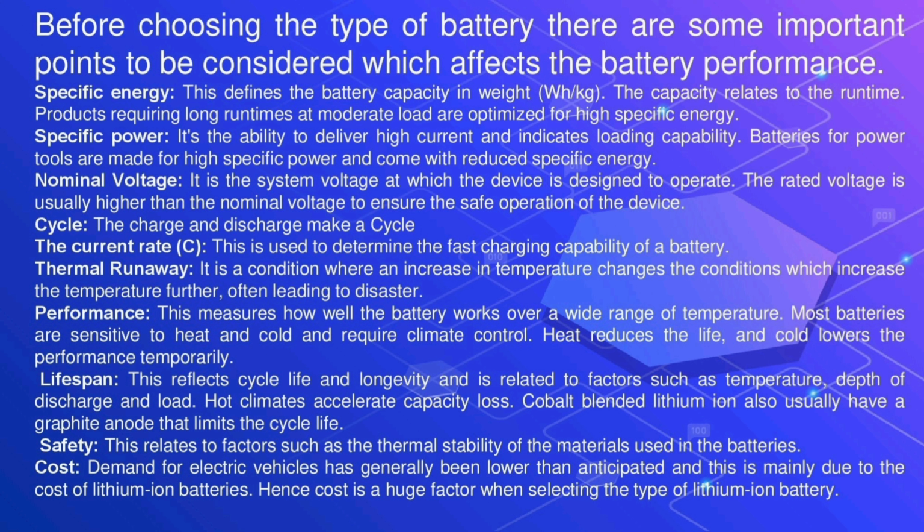Frigid temperatures in particular can substantially hamper both the battery's performance and its ability to accept a charge. What's more, while gasoline engines generate large amounts of heat that can be harvested to warm a car's interior, an electric vehicle's climate control system relies solely on battery power. A recent study found that when the mercury dips to 20 degrees Fahrenheit and the vehicle heater is in use, an average electric vehicle's range drops by 41%.